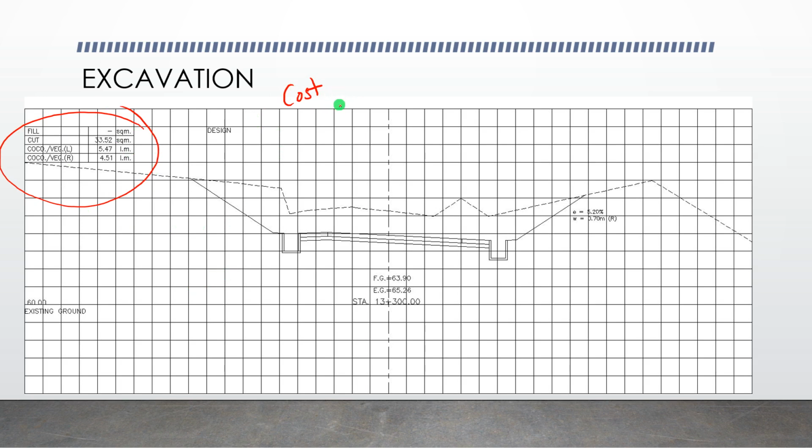in the project. Especially in earthworks, earthworks are always computed in terms of the volume. So if we are in metric, how many cubic meters of soil for embankment, and how much soil is needed for excavation. That's how the cost for earthworks is computed. That's why it's necessary for us to first determine the area of cut and fill before computing the